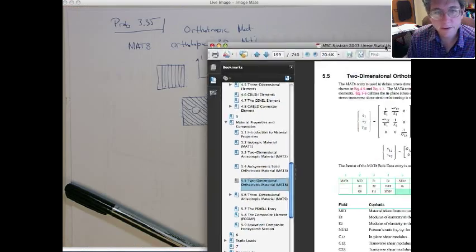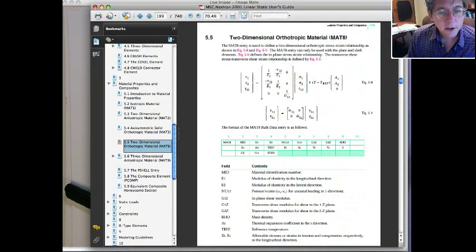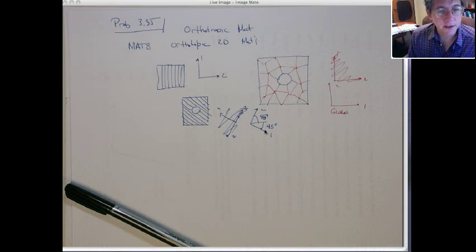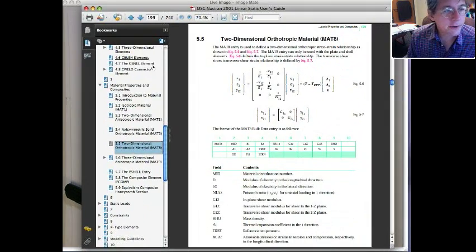I'm sorry, I should just be a little clearer. These are the shear moduli in bending, so these are what are called the transverse shear. You don't have to worry about this too much because our problems are all two-dimensional. You have to just put the G into here, and you can just pick material properties that you can find on the internet. Okay. So how do we do that for each element?